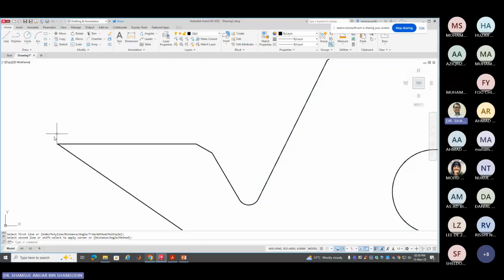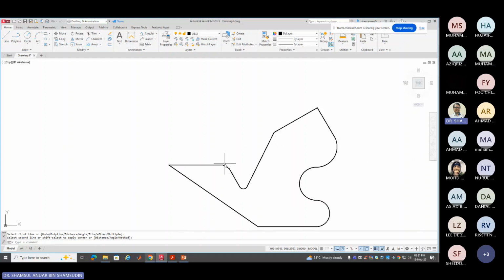Okay. So if I chamfer over here, I'll chamfer 25 here or 25 there. Usually we'll set it at the same distance, or maybe set the angle at 45 or something like that. All right, so those are the things, but because I use polyline, everything is still intact and continuous. It is still a polyline.